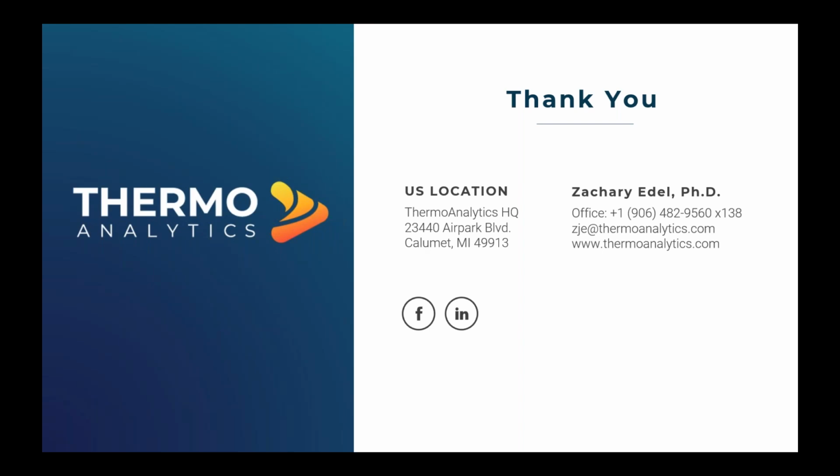Okay. Have you tried any abuse conditions on the battery, like nail penetration, crush, etc.? We've done some thermal runaway simulation where those might initiate the event, but we don't have a mechanical solver. Basically, you would just take the results of a mechanical simulation or a test and impose an equivalent electrical resistance in a distributed model to represent ohmic heating and discharge inside that cell, self-discharge.